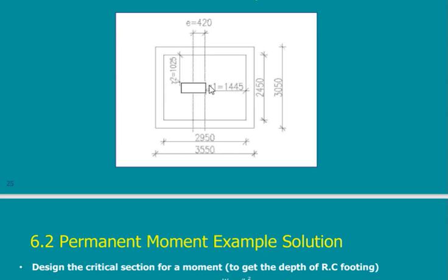So I should calculate, of course, the moment due to this cantilever and the moment due to this cantilever. The other side is not important because it will have the same steel, but the moment of course will be less. So this is the governing moment here, and they both are the governing moment for the steel in the perpendicular direction.